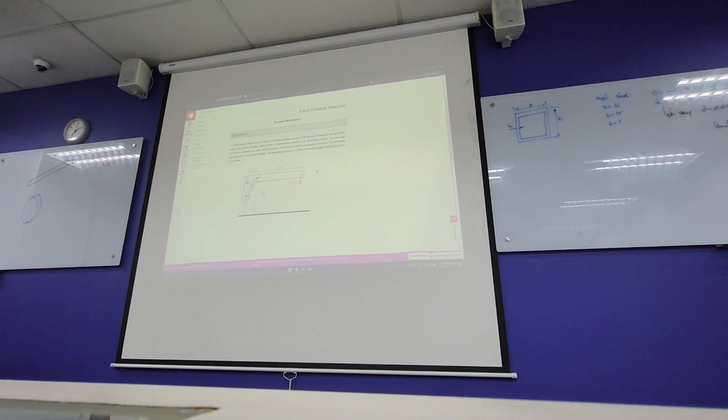Silly example, but let's talk through that. If the limit on deflection is 10 millimeters and you've got a structure that deforms only a 100th of a millimeter, what's that suggesting? Suggesting your structure is too strong, too heavy, too big. So you can go back and change some values, to bring it a little bit closer to the limit.